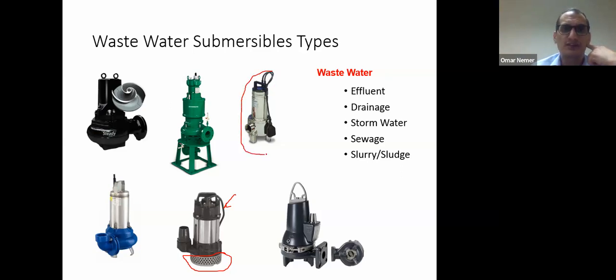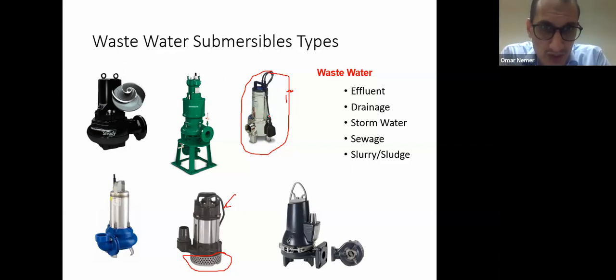Sometimes people ask for a submersible pump with a float switch. You could have it if the pump is single phase, okay, single phase. But for 3-phase, we cannot have a 3-phase submersible pump with a float switch, okay?